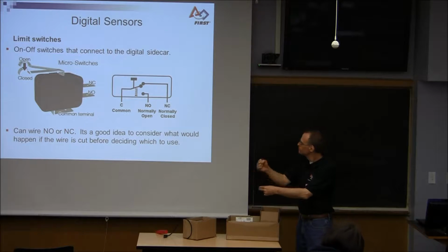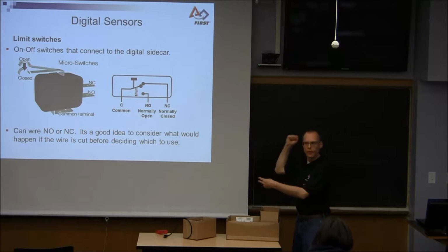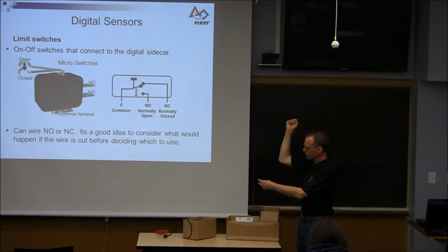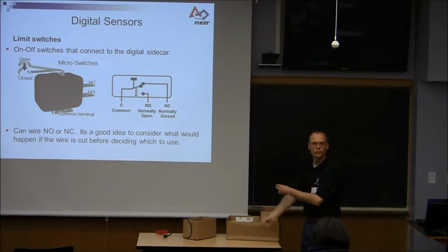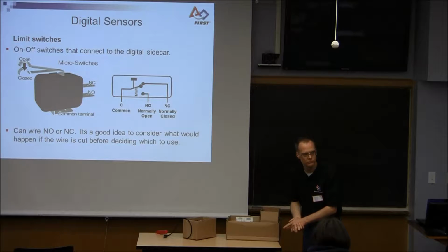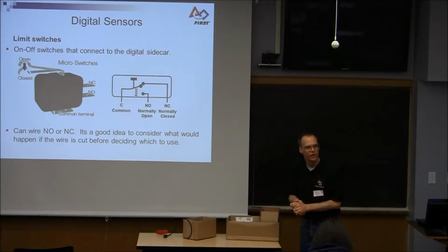But the other way to do it would be to have it connected to normally open, and then it comes down, and when the signal goes high, you have it stop. Now, depending upon what happens if the arm goes too far, which one would be better? One that cuts the electricity to it? Why? If it goes too far, you might break, you might hit something else instead, or?